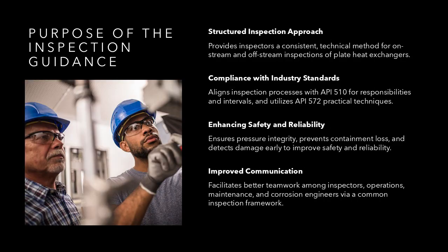The purpose of this guidance is to provide inspectors with a structured and technically sound approach to performing both on-stream and off-stream inspections of plate heat exchangers. From an engineering perspective, the objective is to ensure pressure integrity, prevent loss of containment, and detect active or potential damage mechanisms before they result in failure. This slide emphasizes alignment with API 510 requirements for inspection responsibility, documentation, and interval determination, while also leveraging the practical inspection techniques described in API 572.